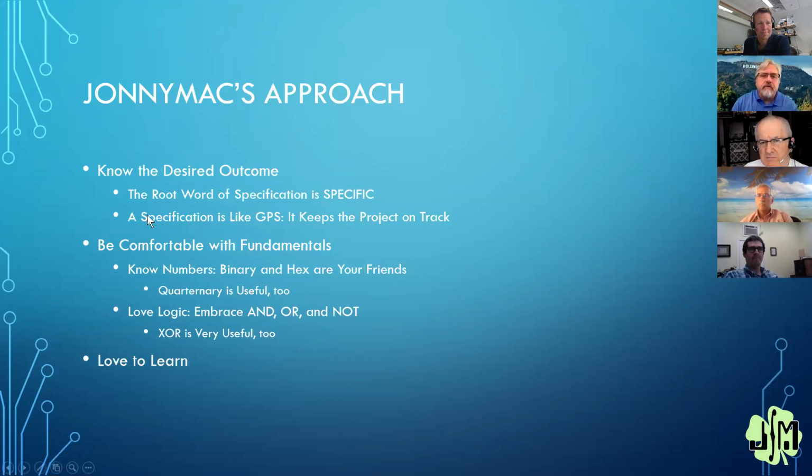And so your specification is kind of like GPS. And this is a phrase I say to my clients all the time. The root word of specification is specific. I occasionally will answer posts in the forums where somebody will say, well, it needs to operate for a short amount of time. No microcontroller knows what a short amount of time is. You have to specify a time in milliseconds or whatever the timing unit is. So be specific.